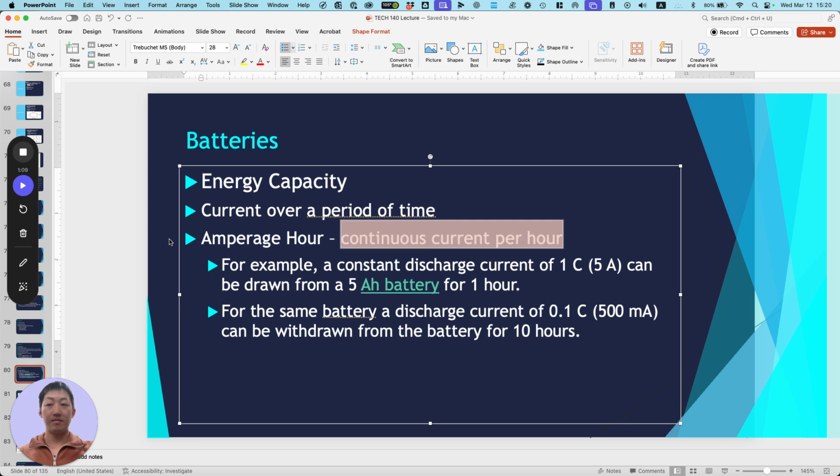Okay, that's this. Battery balance. Internal resistance, I'll have to show you that next time, but that's the impedance that I was talking about. So higher internal resistance means lower performance, more energy wasted as heat. And there's not a number that I can give you like what we have with cell voltages and current. So that's why while we have a new battery, we should record the impedance, which is shown in ohms because it's like a resistance, and then we can compare over time.